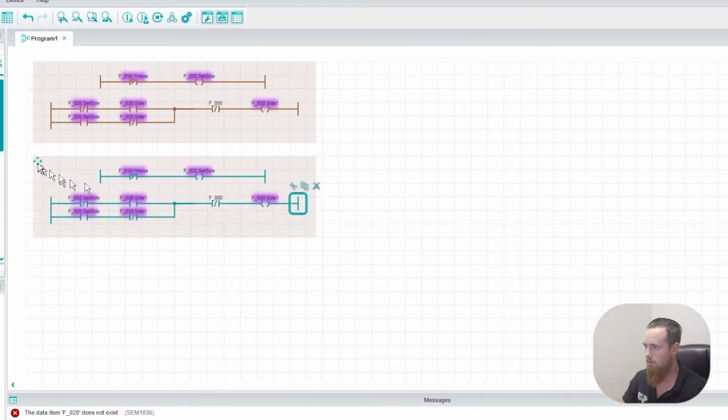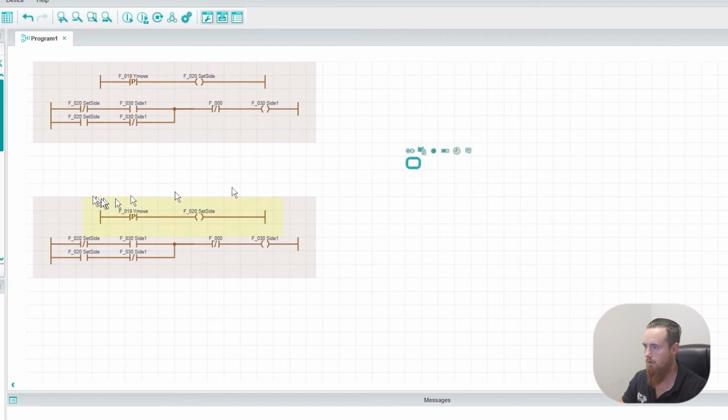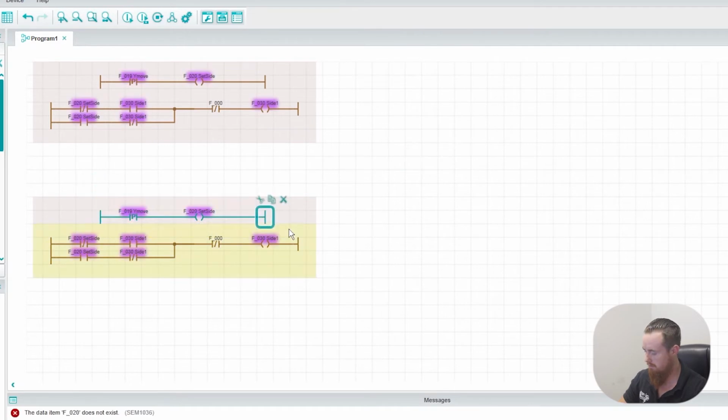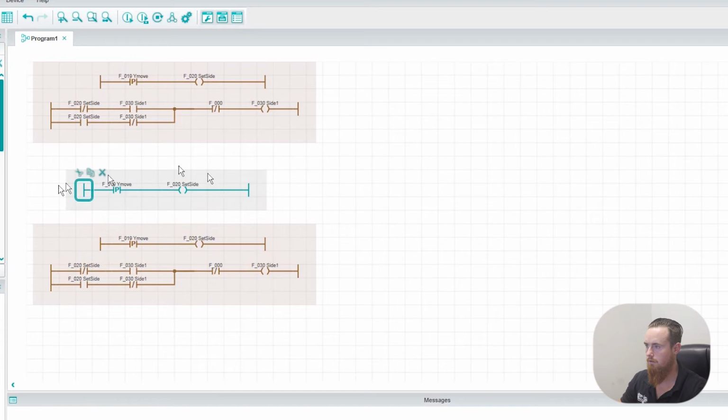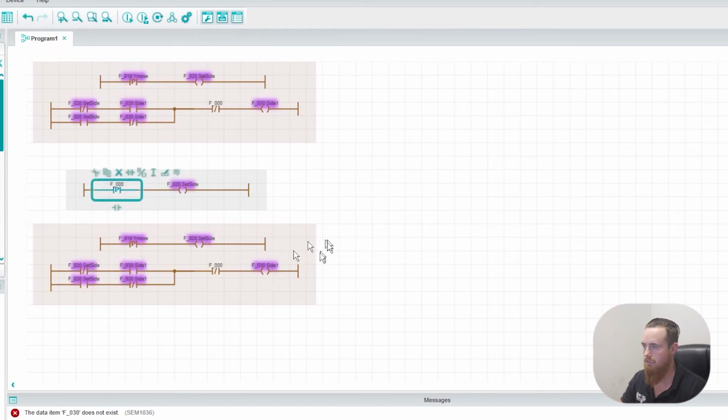We actually need to add one more run of logic to be our activator. So let's just say F0. F's in this logic are flags basically, so they're just bits that you can utilize in here. And so the exact same process basically. So this is not going to be a positive edge either. So I'm going to change that to just being a regular contact. And then this right here needs to be your 1. Then this right here will be the same thing.